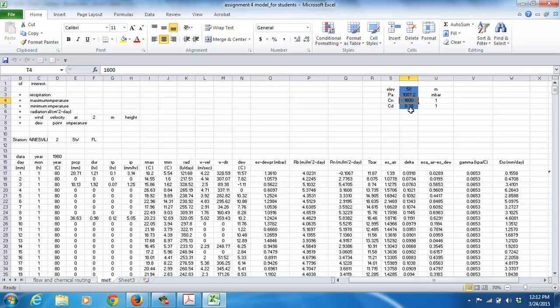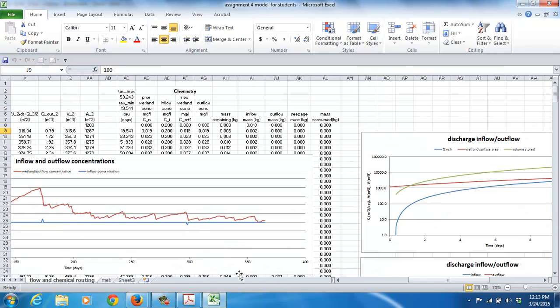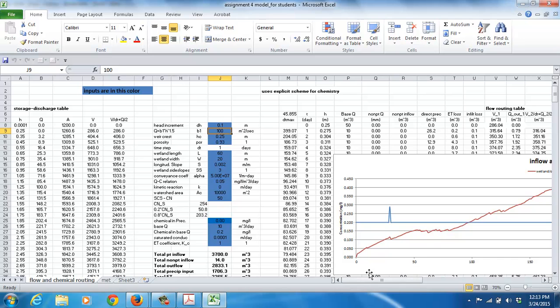The value of CN and C sub D are already given here. These are out of that ASCE standards document, so you don't actually even have to fill that in. That's already given. But you'll need to, of course, reproduce the value on day 173, as I've already mentioned. This evapotranspiration data, for the potential evapotranspiration, and the daily precipitation that occurs, that information is read into the spreadsheet that does the water balance for the wetland.